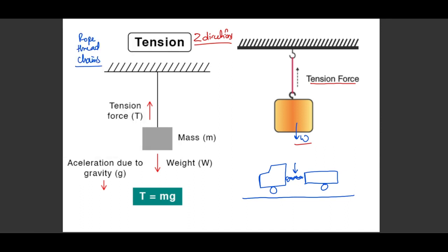Now let's add this idea into the situation. Weight, if represented in this thread, is actually acting downwards, but weight is not a part of this rope, it's not a part of this thread. So how is weight being represented to this whole piece of rope? How does the rope know that there is a weight connected to it? This is transmitted in the form of tension.